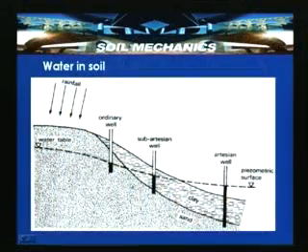For example, if this particular portion of sandy soil is receiving certain water under pressure because of some source of water, either because of some river or lake, then it can be said that it is under artesian conditions. If a well is driven into this particular strata, it is called an artesian well.